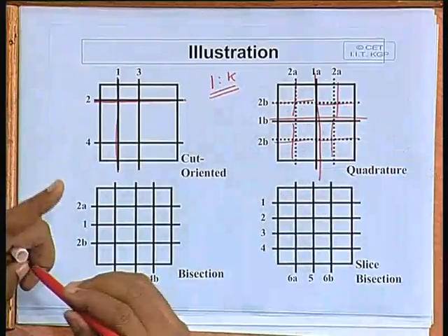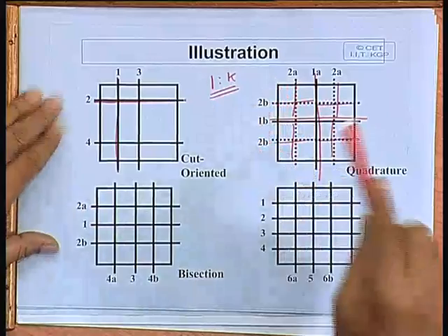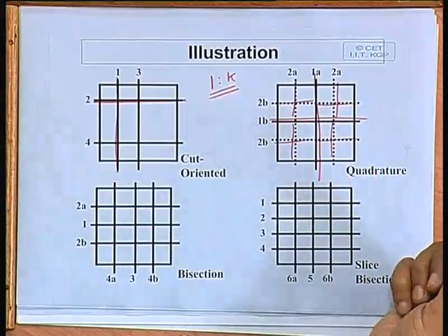For this you can use Kernighan-Lin. Just apply it twice, one after the other. First divide into 2, then 2 into further 2 and 2. Okay. So, quadrature placement can be applied for general cell arrays, like for custom cell designs.